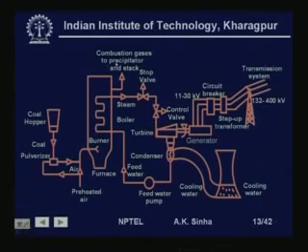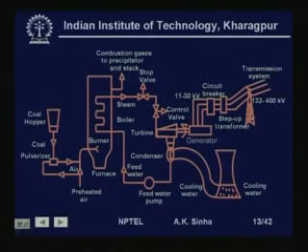Now, in order to reduce the pollution, because the flue gases will also be carrying a large amount of unburned coal in very minute particles. So, you will see the older stations might be giving you some black smoke, but the newer stations have electrostatic precipitators which basically scrub out all these particles in the flue gas, and from the stack you will find a very thin white smoke coming out. So, this is to reduce the pollution.